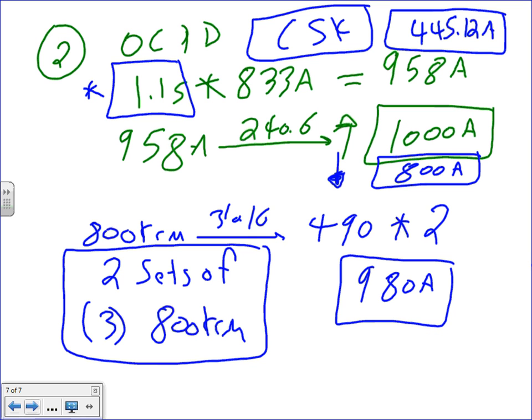Is it too big? No, I just haven't looked at the code, but 800 seems pretty big. Did you look at the voltage though? The voltage is 240 single phase. Maybe you're thinking of 480/277. Yes, it is single phase. It's huge; you wouldn't find it at this voltage. It's a 240, 200 kVA. You're not going to find it at this voltage.